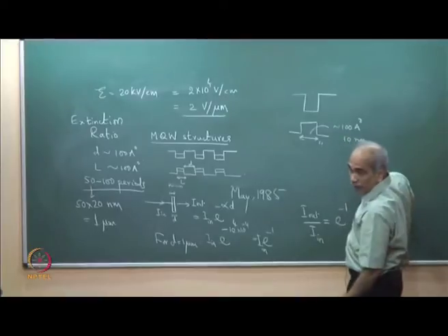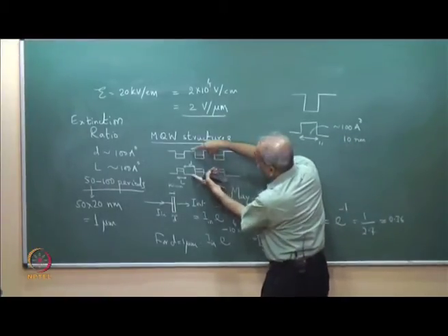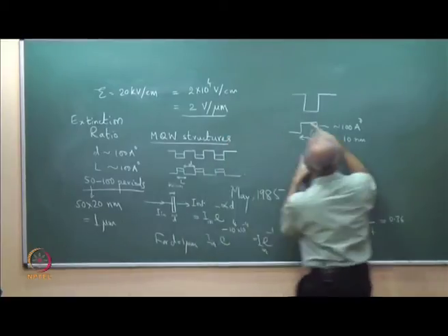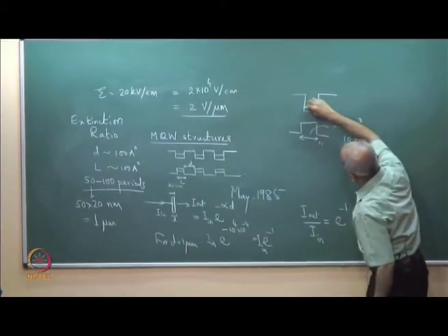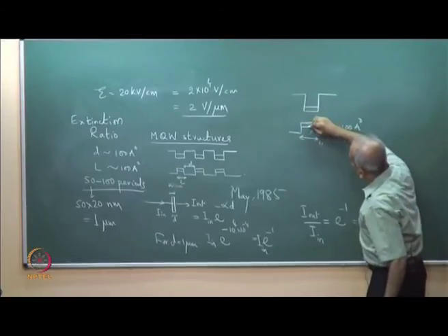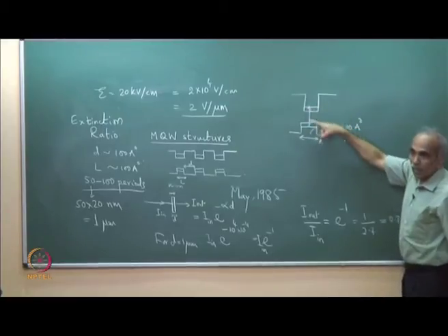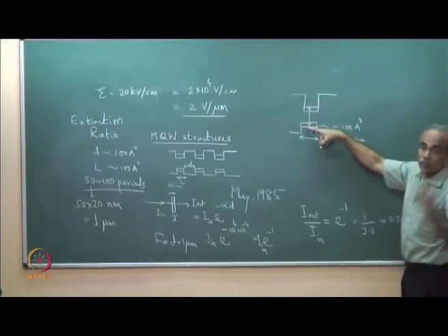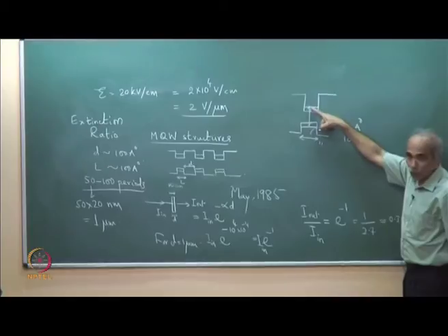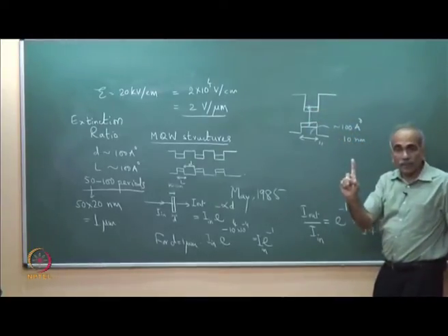Because the photon energy corresponds to this band edge. Outside, if I take a single quantum well, please see, we had E1 here, E1 dash here. The band edge corresponds to this energy gap. The band edge where the attenuation suddenly starts shooting up corresponds to this, and we have biased it just at the band edge.